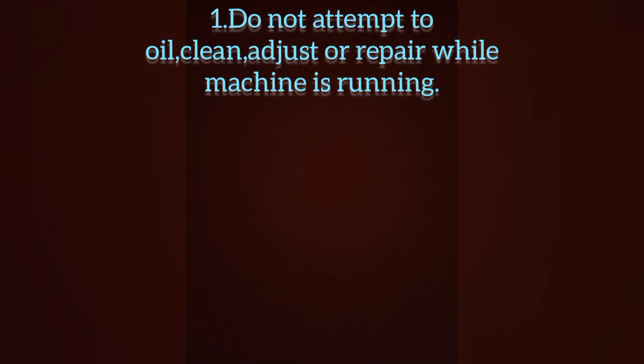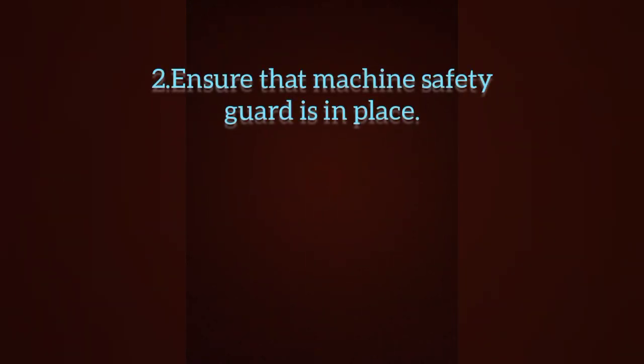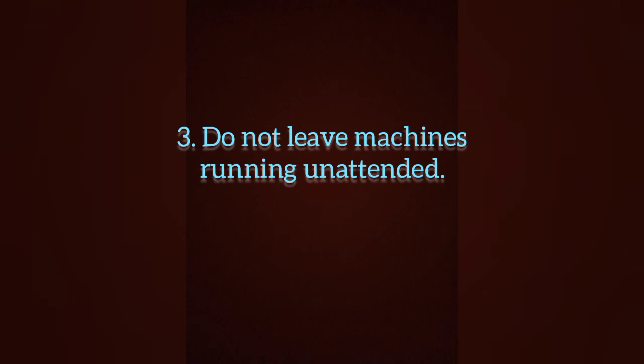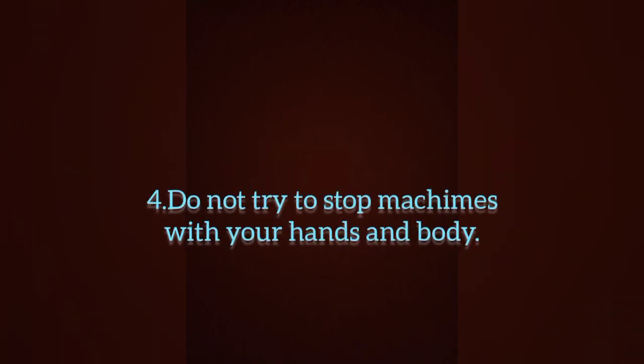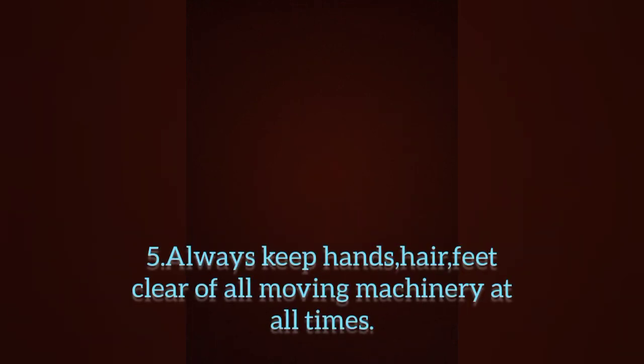The following guidelines apply to all stationary machines: Do not attempt to oil, clean, adjust, or repair any machine while it is running. Ensure that all machine guarding is in place and functioning properly. Do not leave machines running unattended. Do not try to stop the machine with your hands or your body. Always keep hands, hair, feet, etc. clear of all moving machinery at all times.